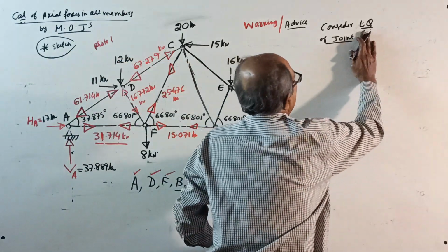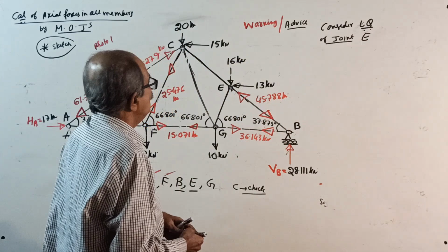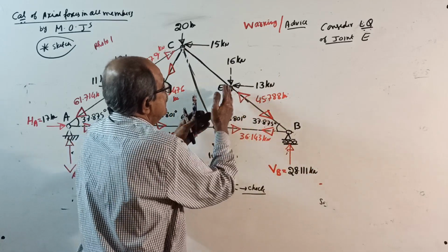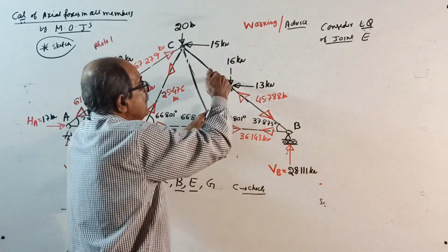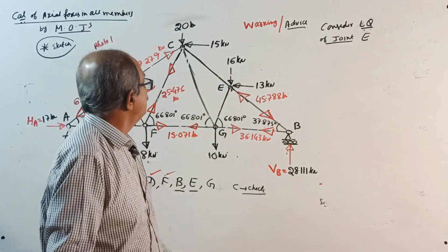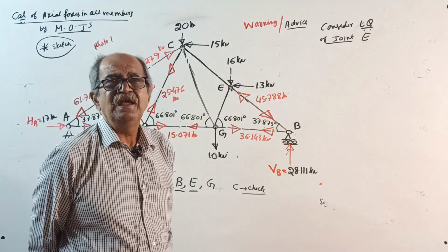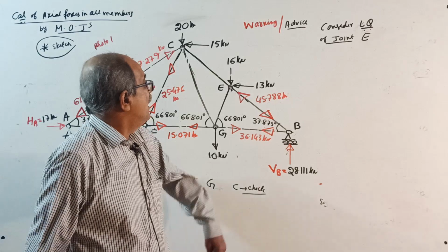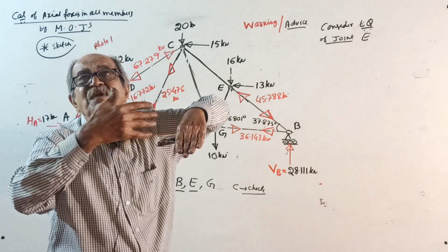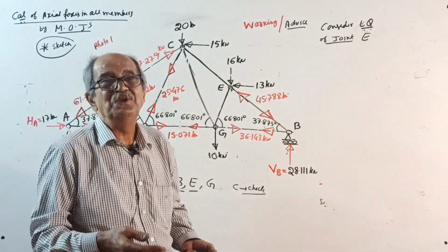Okay. E. Now at joint E, I can do one thing. I can resolve perpendicular to this member, get this force, then resolve along this member and get this force. But you don't try it. Dangerous. So therefore I can give the direct answer. If both are inclined, for me the calculator is sufficient because I will resolve first perpendicular to one of the inclined members. That will go, the other will come. Resolve along that one. That way I can do it, but you never try those things.